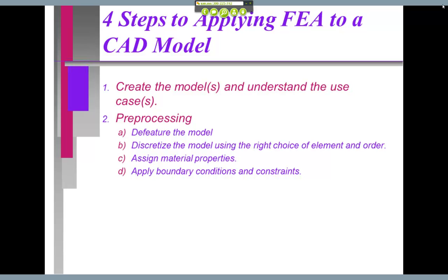So the CAD process, the first thing that you have to do is think about defeaturing your model. More than likely, your model has some edge blends, some fillets, some radii. It may even have some holes in there that you're not too worried about. The holes are attachment holes. They really don't need to be there. We can put a load right at that location.